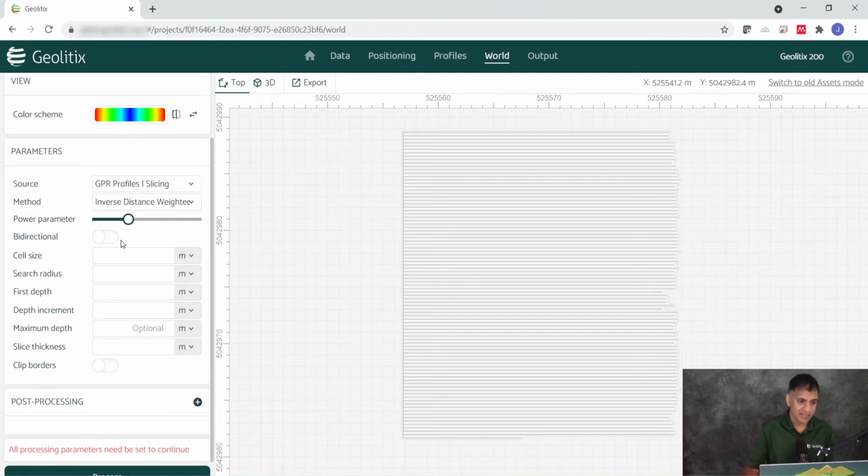Our cell size now, apologies, this original survey was done all in imperial. I am Canadian and thus can only think in metric, so I'm leaving mine as in meters, but you can do other units for the Americans and I guess Brits sometimes, who are still in archaic measurement forms. And I will go down to 1.5 meters. There's probably no point going deeper than that.